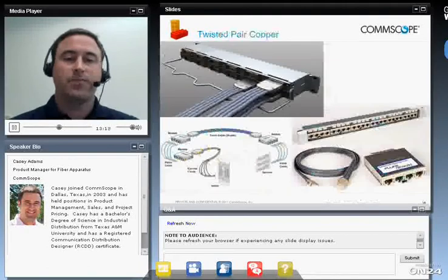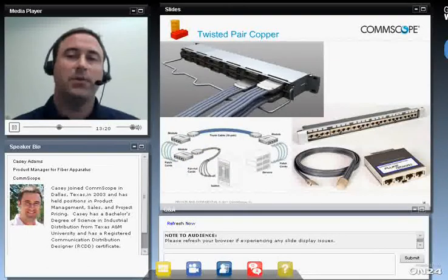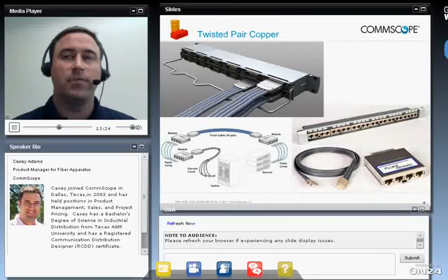Densities on trunk cables range from 12 fibers up to 144 fibers in a 12 fiber increment based on MPO. These trunks are built using OM3 and OM4 standards compliant glass. This ensures that the backbone to your system will have plenty of performance over time as applications change.